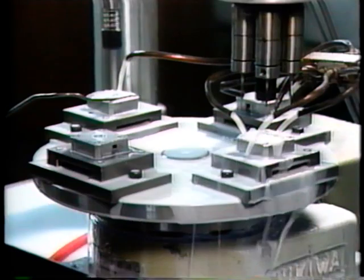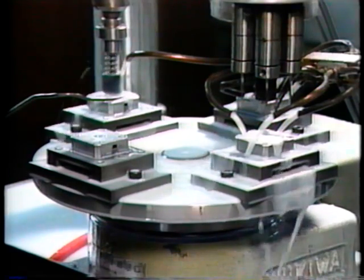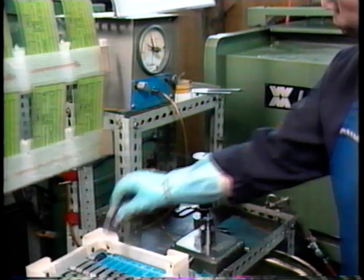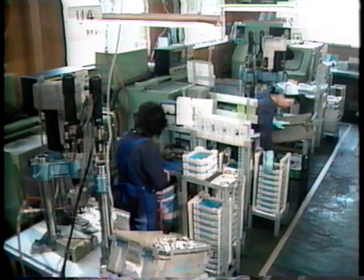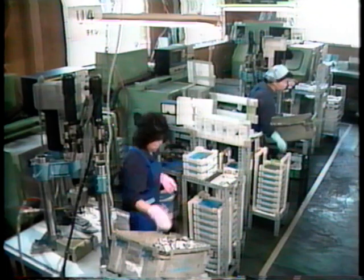The tables for the drilling and the tapping used to be separate. Now we have a U-line and we can work on 2 items at the same time. 2 tables have become 1, so it takes less time. That means we have more time to check for defects. In fact, we have now managed to get down to 0 defects. The creation of these U-lines for immediate processing also had the effect of reducing the necessary workforce from 6 operators down to 4.